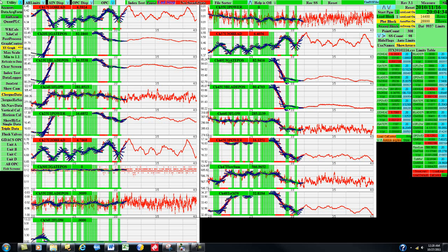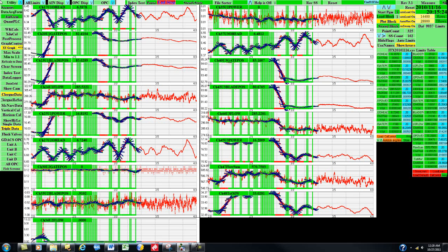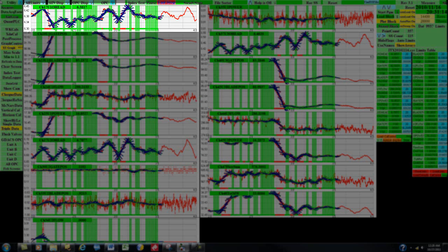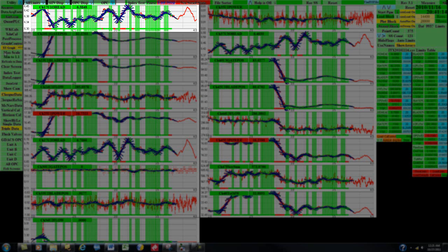A data point is deemed steady state if the slope and standard deviation values are less than the predefined limit values in the table. A vertical green line is drawn through all of the strip chart panels to show that a steady state point has been detected. The vertical axis of each of the strip chart displays is automatically scaled to fit the range of the data in the 2-hour block for that parameter.